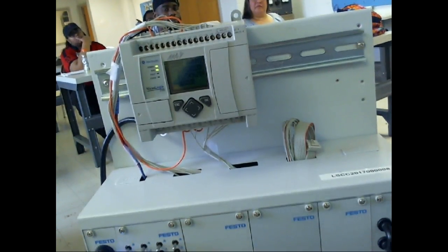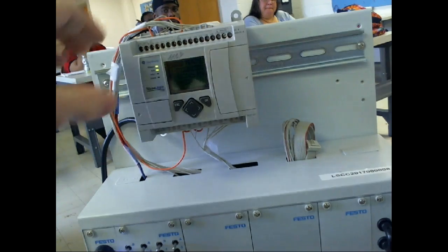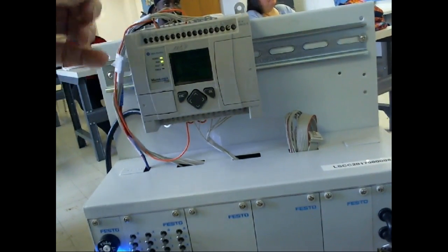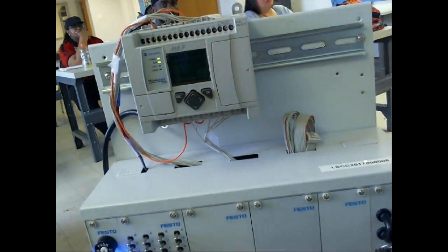Now, why they do that is so you can run these devices off an external power supply. You don't have to run them on the power supply that's part of the PLC, right? You understand? Because that little tiny PLC can't provide a lot of current, or power. You don't understand that? So what we would do instead of jumping the power supply here, I could have taken the minus here and jumped it from there to there, and then I would have had to take this positive and run that out to my devices, right? You understand? Yes or no? That makes sense? Yeah. So we have this hooked up, and I'll have a diagram in a minute.